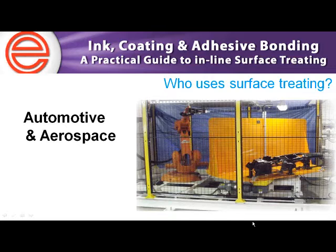Likewise, you may have a dash panel on a higher-end car where they actually wrap it in leather or some other sort of material, and they will inject a foam between those two. To enhance foam adhesion there, they use surface treating as well. It can be used on door panels on cars for foam applications. It can also be used in the headlamp of a car where we'll actually trace the glue track to get better bond adhesion between the front and rear pieces of plastic on a lens or a light for an automobile.